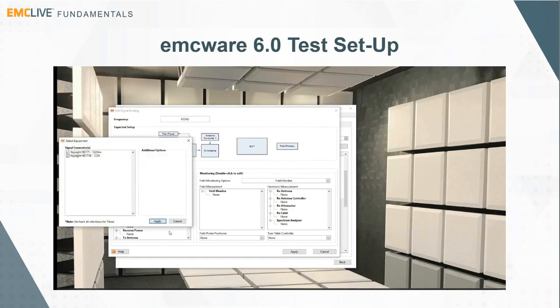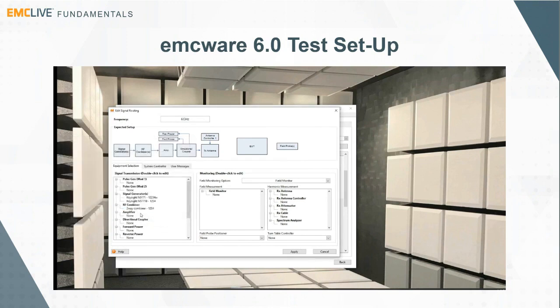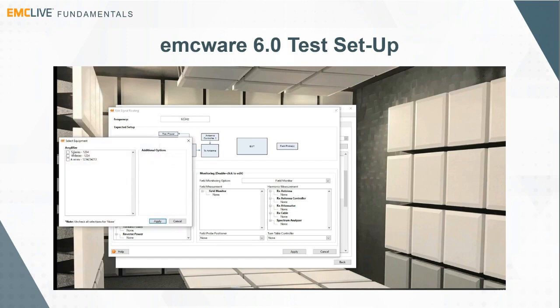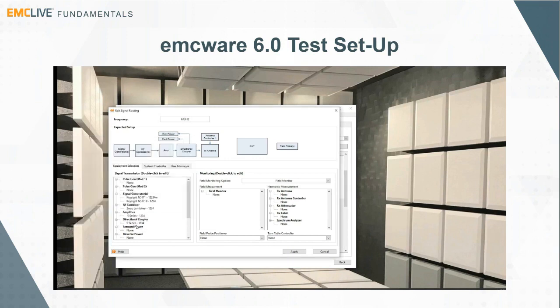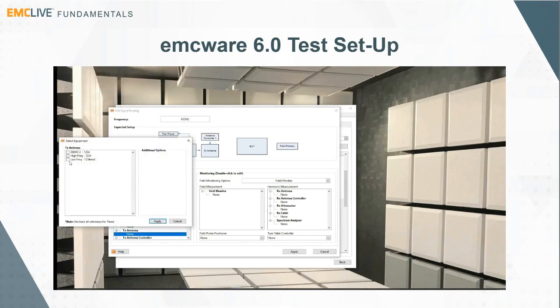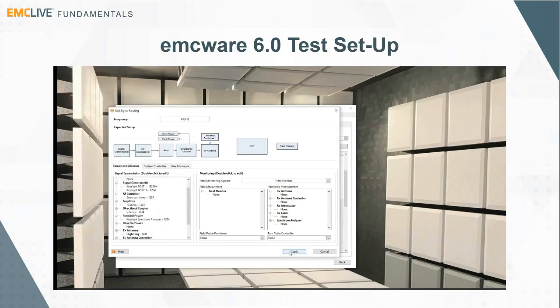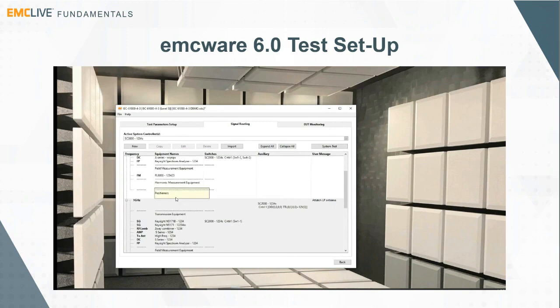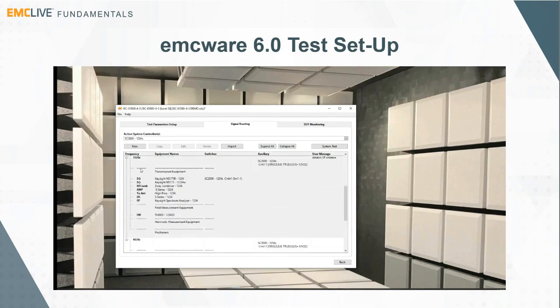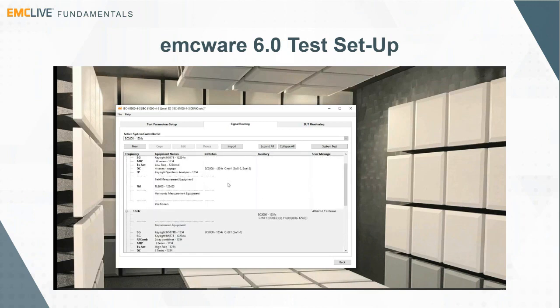Signal generators, combiner when we're doing multi-tone, the amplifier for this particular band, we'll also set up an antenna, and a power measurement instrument, which is our spectrum analyzer, as we've mentioned. So now we have a breakpoint starting from 1 gigahertz going to 6 gigahertz using a different amplifier and antenna pair.